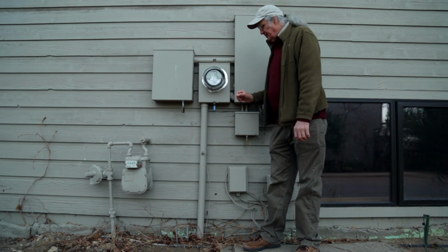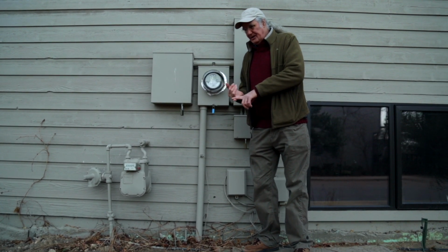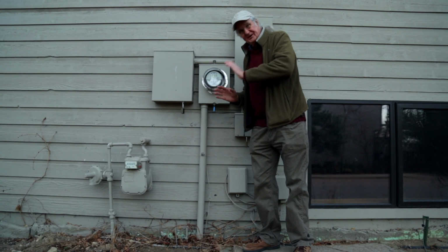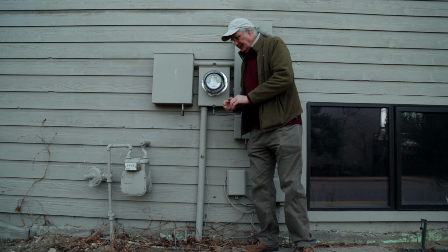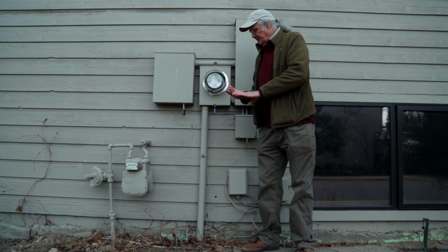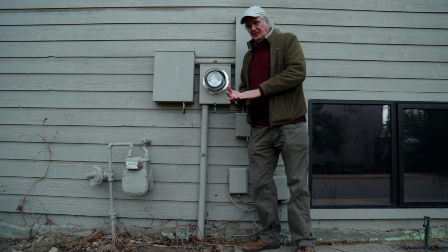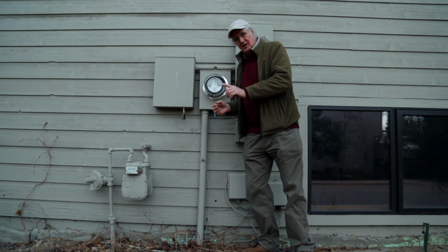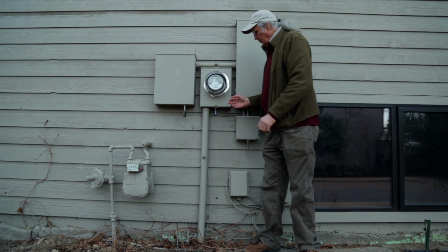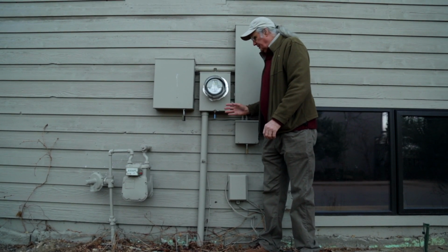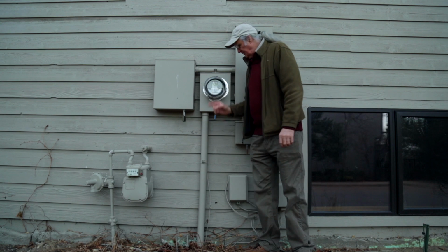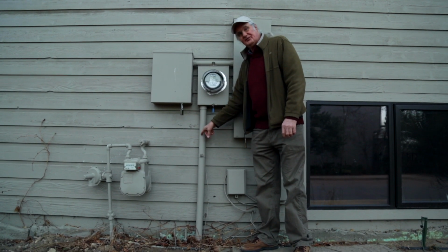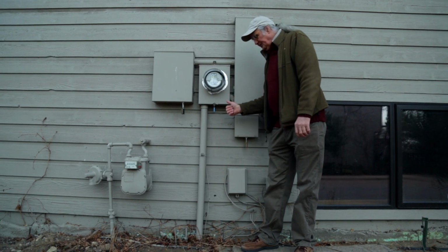However, when you have parallel paths, which include metal water service supply pipes, which are grounded for lightning to get into the earth as the system ground by code, and the sheathing of TV cables, sometimes telephone lines, and then sometimes the ground wire to pool equipment. These are all parallel paths that return current can flow on to get back to the neighborhood transformer. When that happens, that current that's on these other paths is not here. There's a deficit between the two.